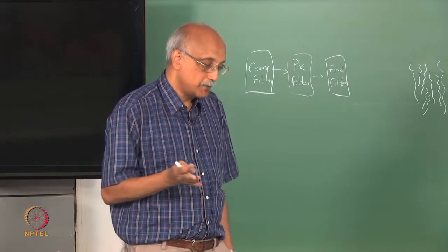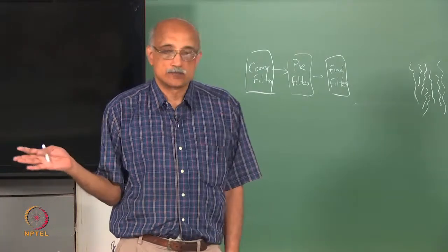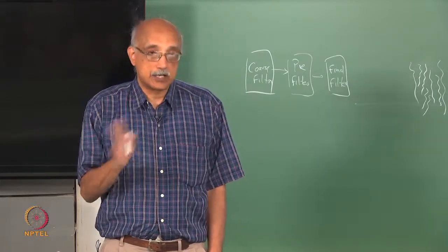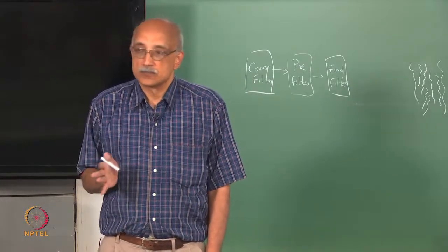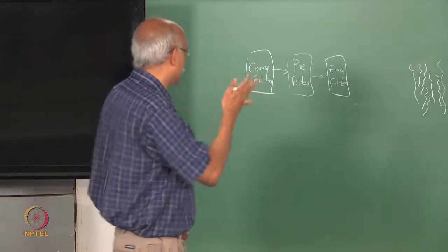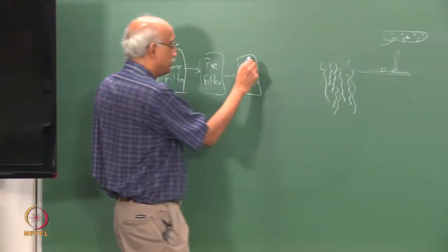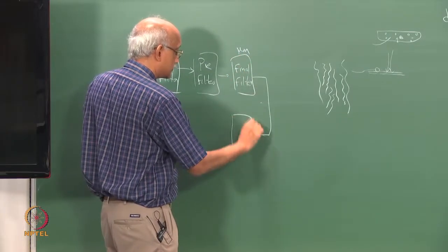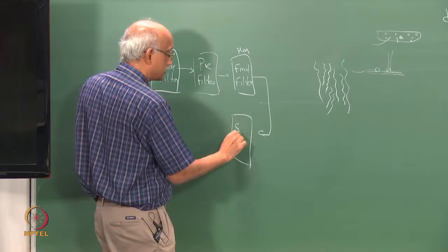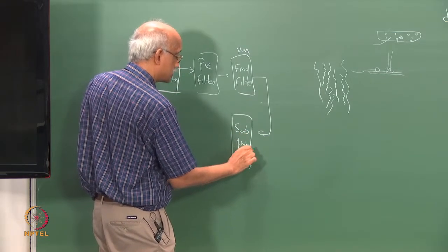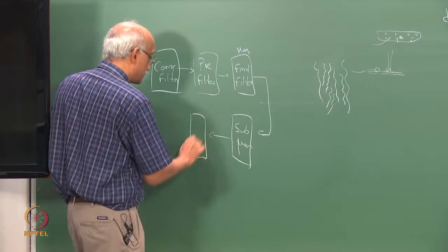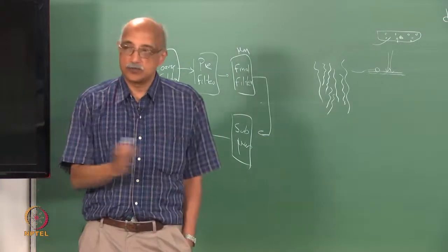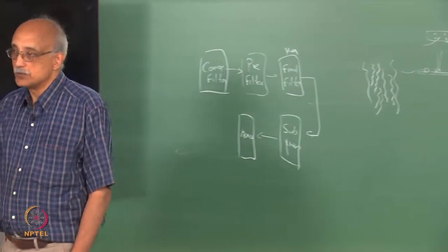A membrane filter can be made all the way down to nano sizes. There are nano filters available in the market. Again, you do not want to use a nano filter as a standalone filter. Typically, the final filter usually will filter down to microns, and then you would have another final filter that filters down to submicrons, and then you will have a nano filter. So, if you are trying to achieve nano level cleanliness, you need minimum of 5 to 6 stages of purification,